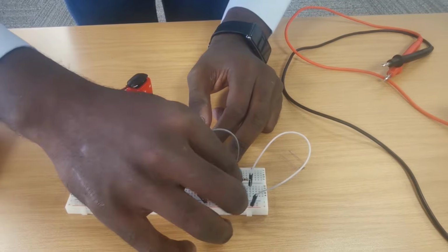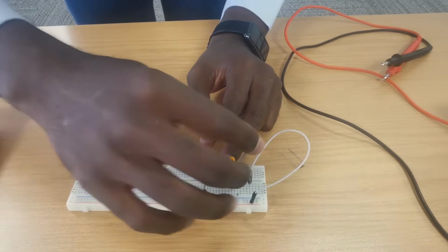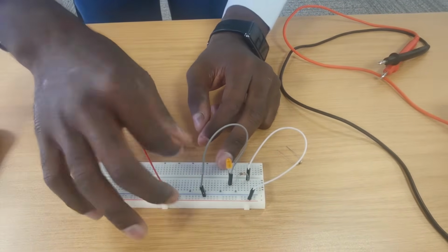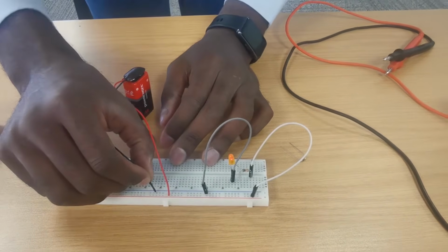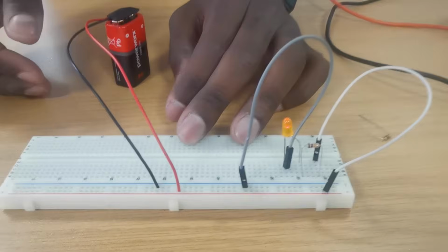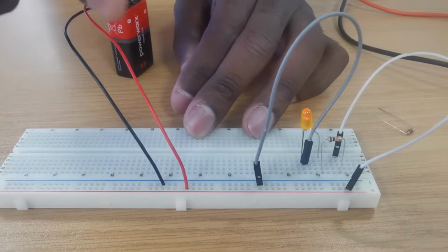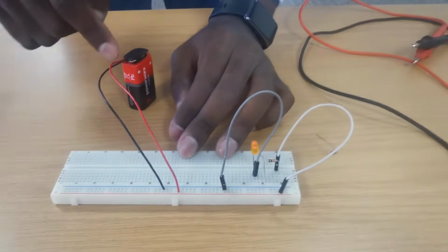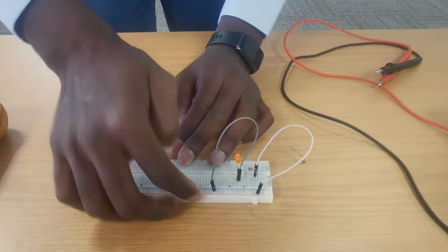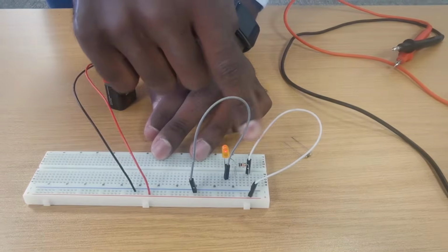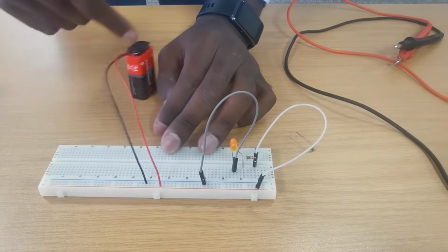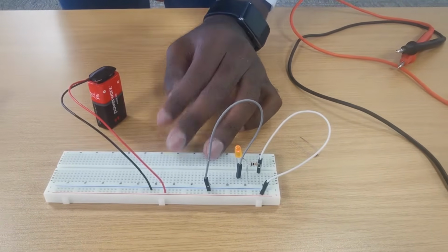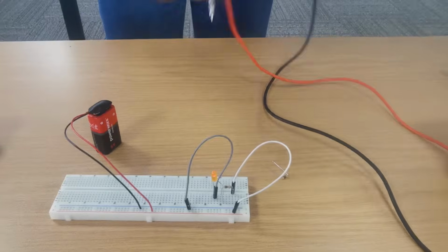So I'm going to connect now the output of that circuit to the negative. And when I connect this negative leg now, it should actually switch that diode on, which is what you see there. So the diode goes on. So now I know that the whole circuit, from the positive, it goes to the resistor, and then from the resistor it goes to the diode. From the diode it comes to the negative of the source. That's a complete circuit. And I can again measure the voltages.